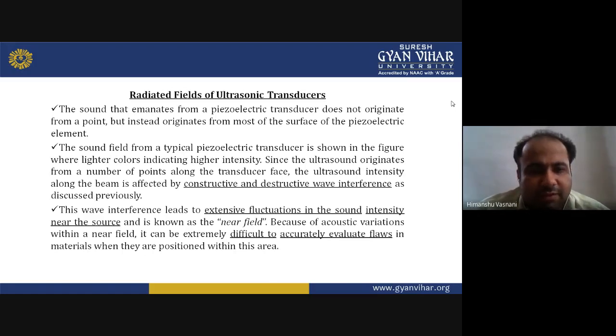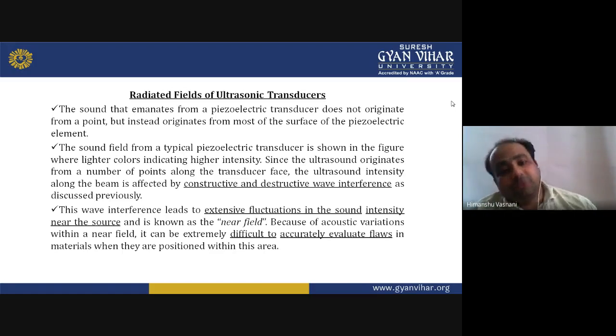When the wave interference leads to extensive fluctuation in the sound intensity while testing near the source, it is called near field. Because of acoustic variation within a near field, it can be difficult to accurately evaluate flaws in the material when they are positioned within this area.